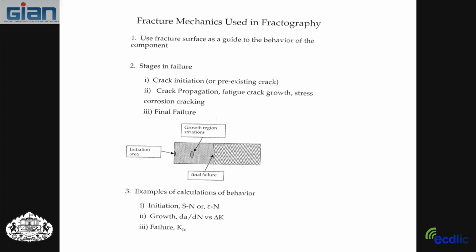You can look at the fracture surface. You imagine then a wall that had broken in two, and you're looking down on top. And one of the things you might see is a black area. You might see a shiny area that is looking like fatigue. Fatigue often comes out shinier than fast fracture.